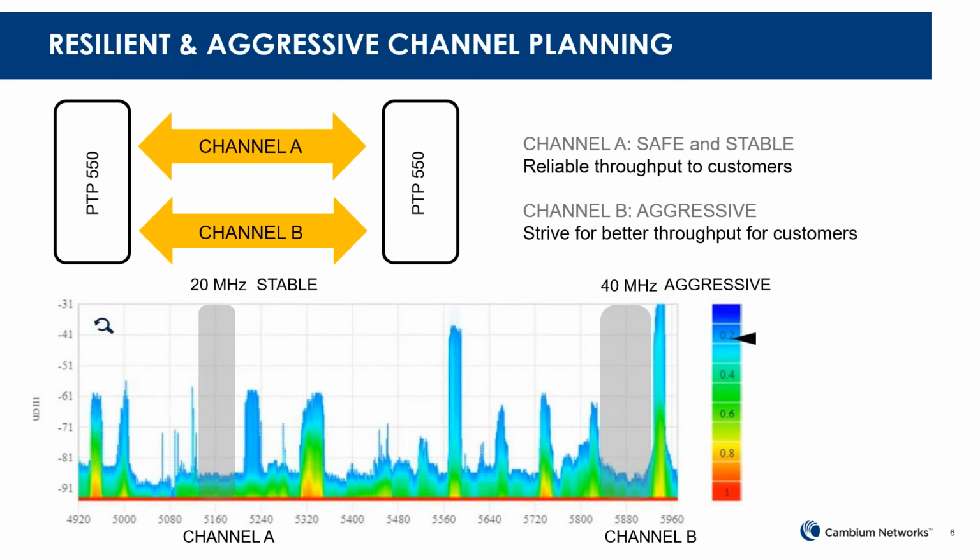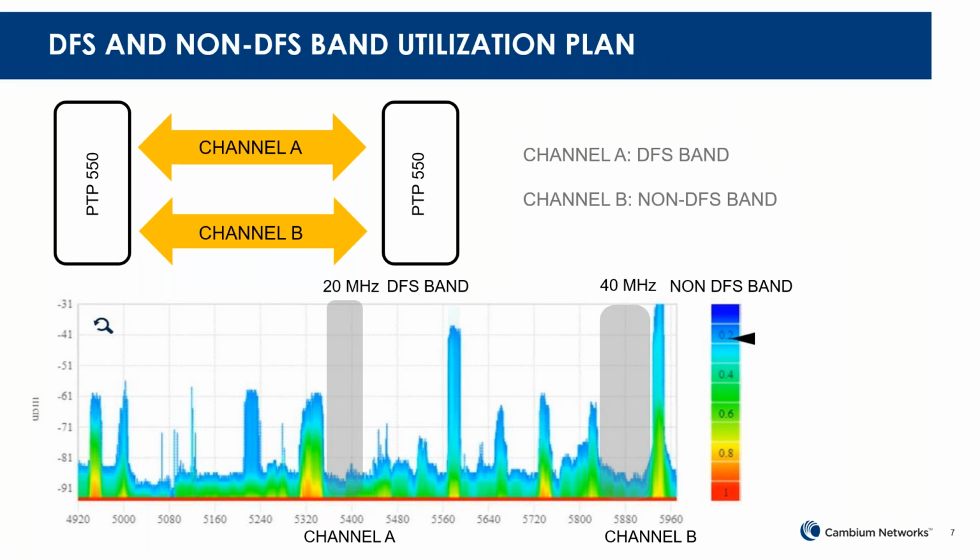And so this is resilience, or how you do the channel planning thing. If we have DFS, for the DFS, when we have detected the radar, the radio has to shut down and wait for a certain period before it can retransmit.